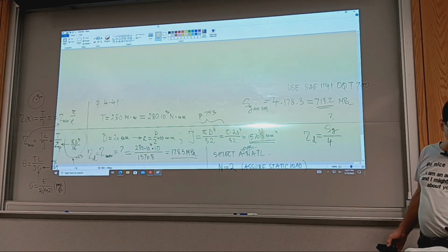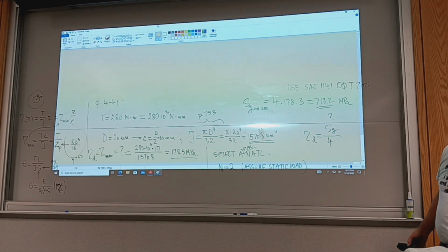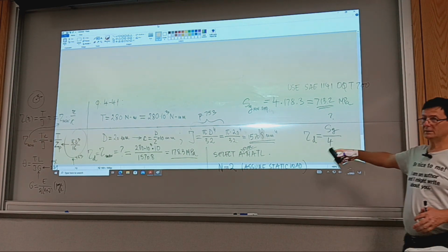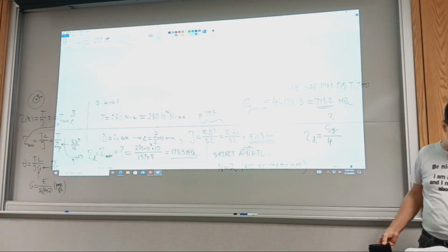If you look at the figure now, you see that there's a profile key set. What does that mean? And we also have a retainer ring over a diameter. Is the diameter specified? It's missing a diameter, but there's a dimension there. However, below the blades, you don't have any torque transmitted. Does it make sense? You're still taking notes about this? Okay, you can take a picture of this, and we can move to problem 40 now.